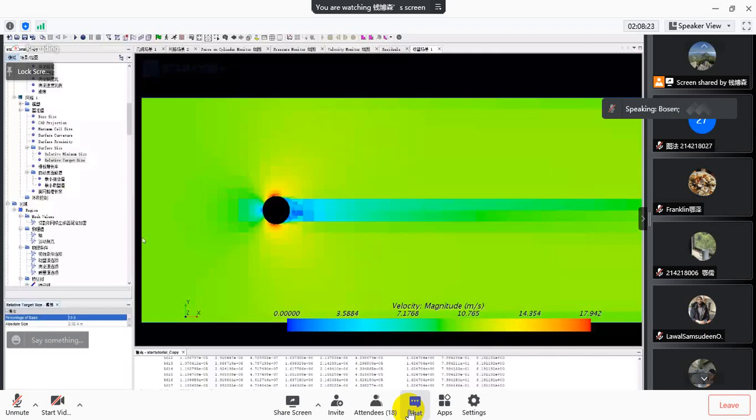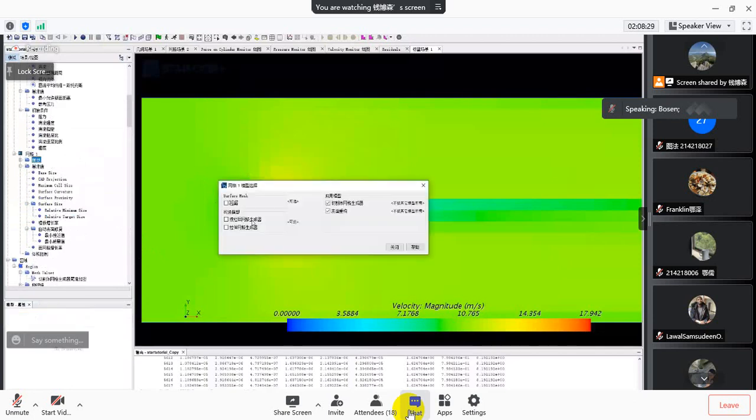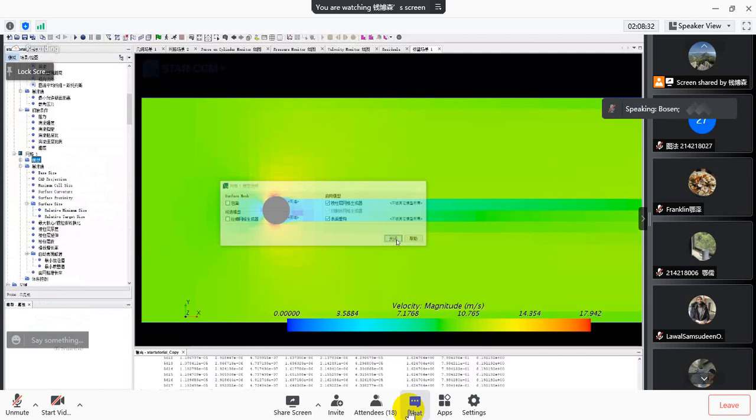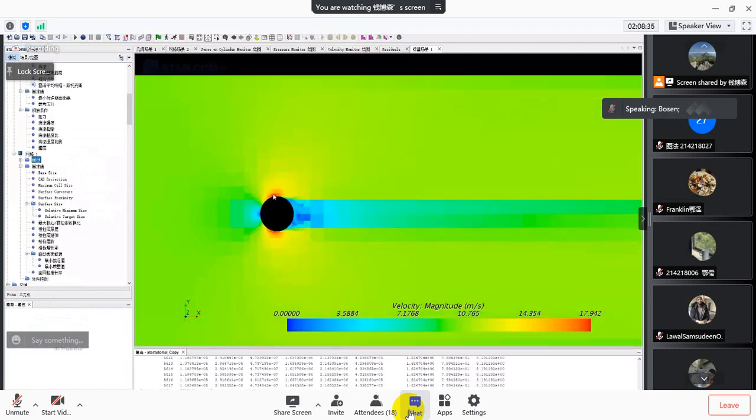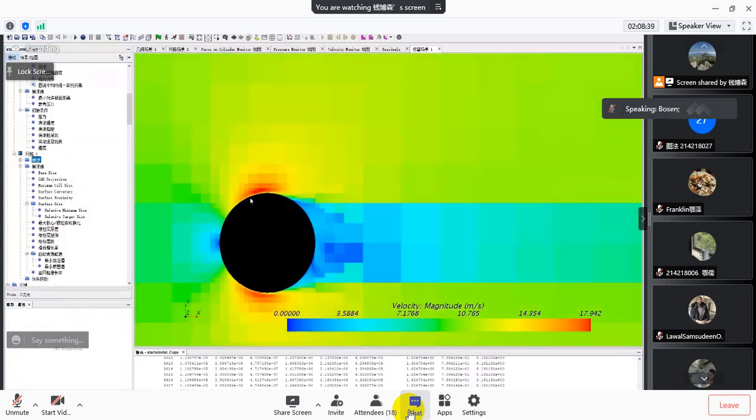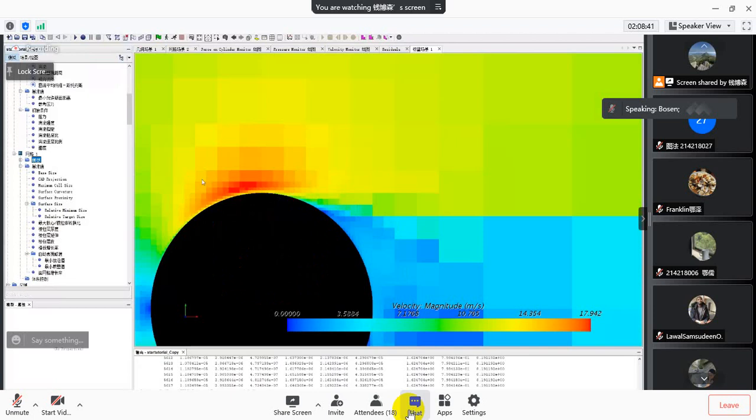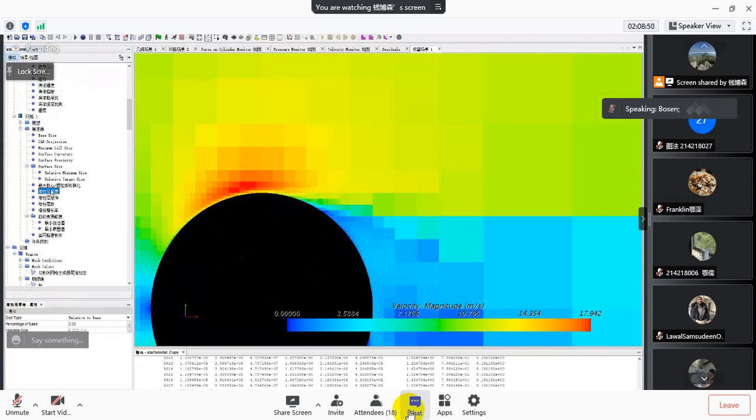I'm sorry, before that, let's add another model, which is the prism layer. This prism layer corresponds to the large velocity gradient on the peripheral region of the cylinders. Then we have the thickness of the prism layers. This thickness corresponds to a y plus value calculation, so it's like what Eze just asked in the beginning of the class. It's all based on trial and error.